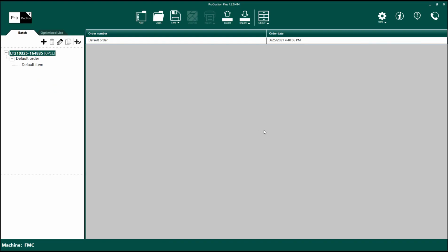It is also possible to load a CSV file with a list of articles with all the data like colors, description, quantity, and variables, just like for an ordinary list. In order to add a CSV file with an article list, just click on Import and select Article List.